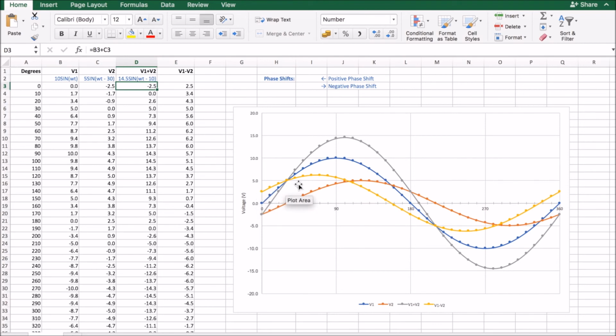We can see here that the yellow trace reaches an amplitude of around 6.2, looking at the caption there. And likewise, we get to a minimum of around minus 6.2. So that's going to be our amplitude, 6.2. But again, looking at the phase shift here, and again, it's easier to see it at the center point here, we can see that in this case, there's a shift to the left.